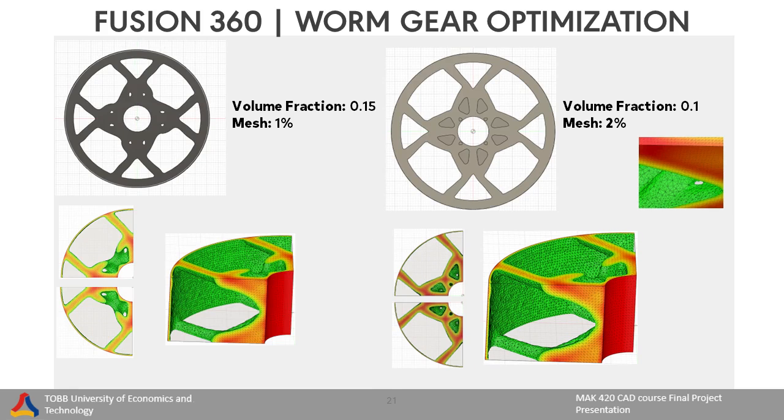Afterwards, the system continued to be optimized by reducing the volume fraction in the quarter-scale gear. Whenever volume fraction decreased, the gear started to lose weight, but for torsion, we should stop it somewhere. In the last step, we were curious about comparing the quarter-scale gear and the 1/8 scale gear at 0.1 volume fraction and 1% mesh. It has been noticed that the narrower the scale, the greater the torsional resistance of the created gear.